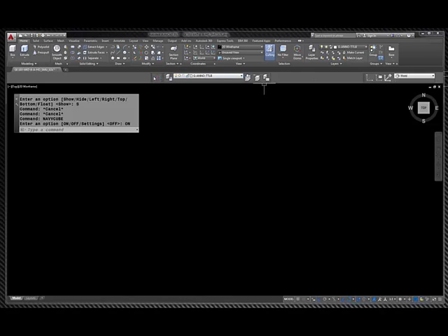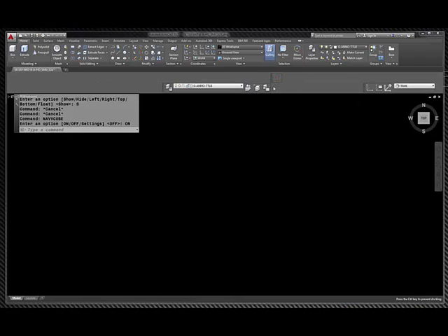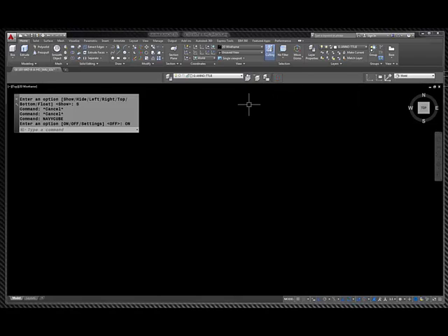So I'm going to move my little toolbar, and we're going to be building my toolbars as we go along. I want you to see how I do that. This UCS2 is the same thing as this little window here in coordinates. But I like it right here because it's right next to my view cube, so I can jump in and out. If I change something, if I go into my home view and I realize I want front, I can just go right up above and go to front.